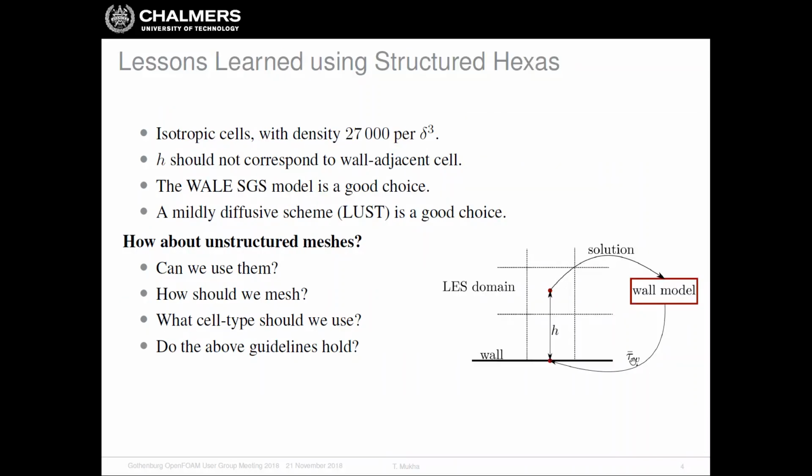So during my PhD project, me and my colleagues looked quite extensively at how to make wall-modelled LES work well. How do we set up the case so that it produces accurate results for us? The majority of those simulations we did were using structured hexahedrals, which is generally also what people mostly use nowadays with large eddy simulation in general, but also with wall-modelled large eddy simulation.